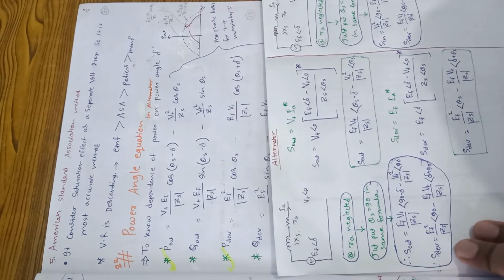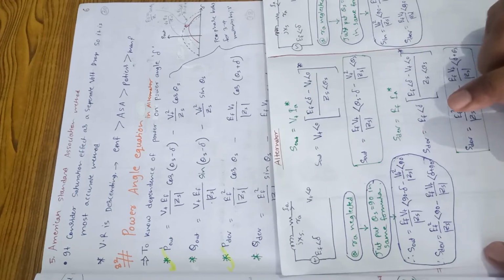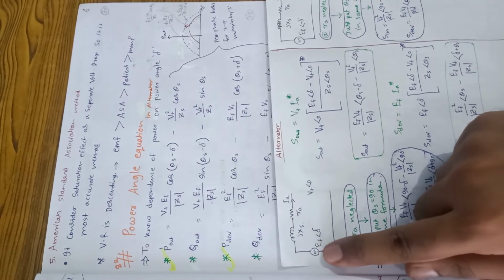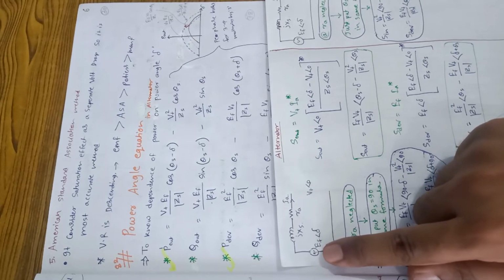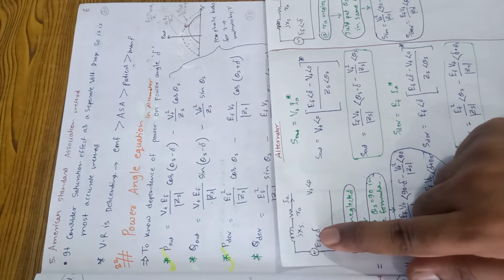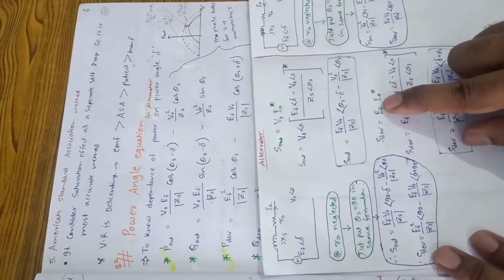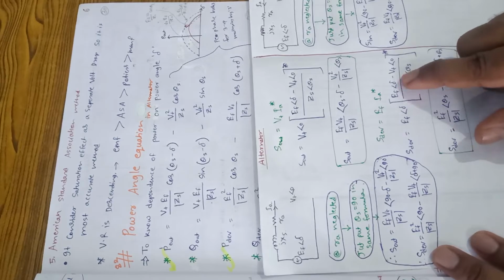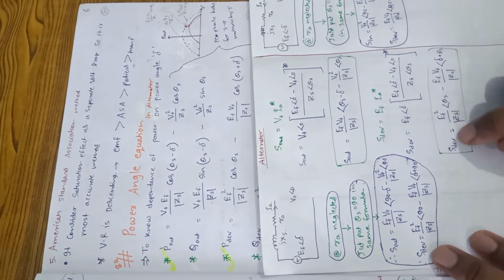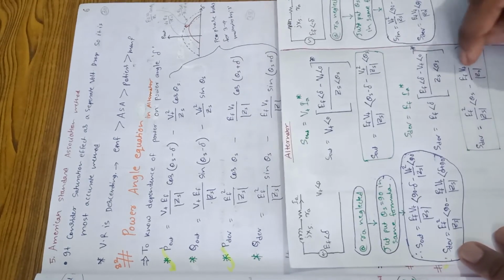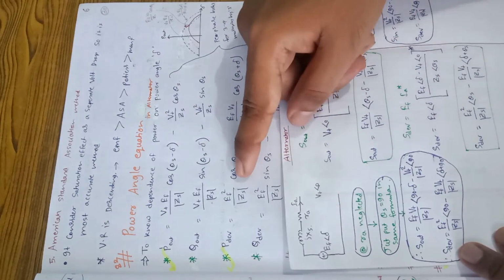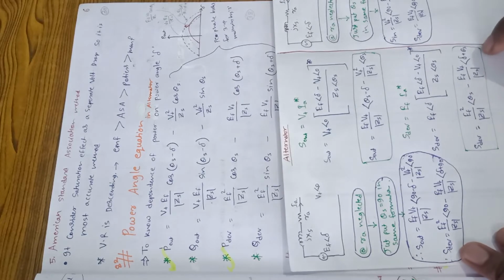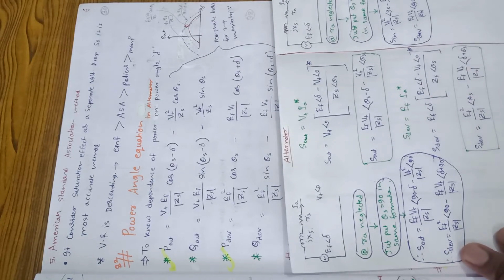After that, when we talk about developed power, the power is developed at the induced EMF. Developed power will be EF angle delta into I conjugate. We know the equation for I, so we just put it in and simplify and we get this expression. Similarly we can write the equations very easily. This is what we need to keep in mind. You can easily derive these equations.